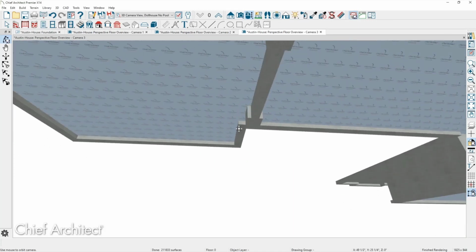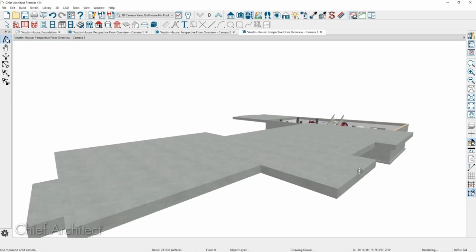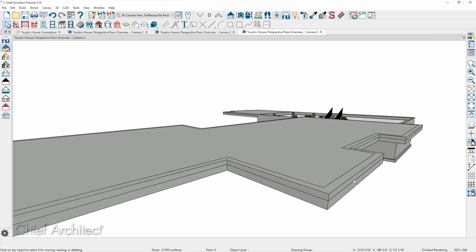Well, let me help you out here, because I think this is where the problem comes in. I've got a 1-foot stem wall on top of my footing. Okay. So the 1-foot stem wall, in other words, your picture doesn't work because the footing's actually down 12 inches from a stem wall. Okay, so your stem wall is popping up 1 inch above here, right? No, it's at the bottom of the slab because the slab sits on top of the stem wall, or flush with the stem wall. But my minimum stem wall is 12 inches.